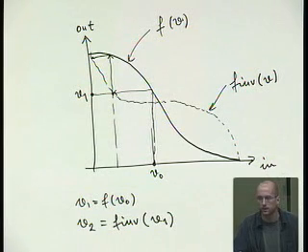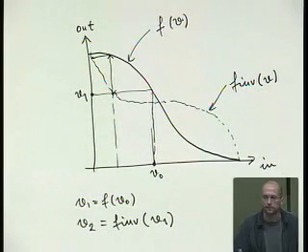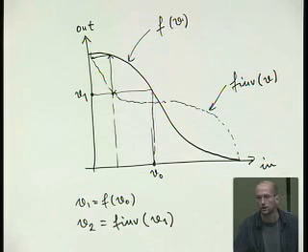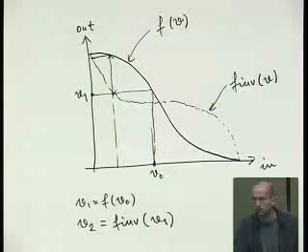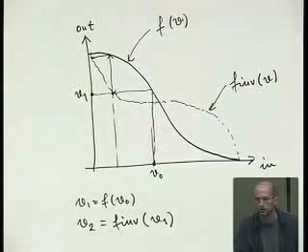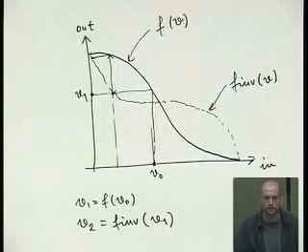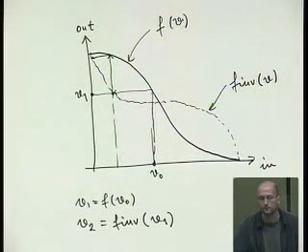When you're, for example, working with a chain of gates that implement a clock tree, you commonly have a situation when you need to analyze a buffer tree that is built out of inverters. So you have a chain of gates with the same property, and then you can basically just assume that they all have the same transfer characteristic. If not, then you have to work apparently with the transfer characteristic of each individual gate, but that still follows this analysis, this concept in general.